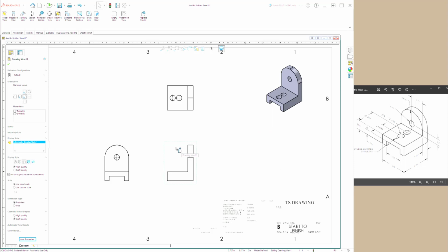So what it's telling us is that in here, it's in the hidden line remove. We want to show the hidden lines. So we want to make the hidden lines visible. On the left hand side, when I click the view, we want to choose hidden lines are visible, and bingo, the hidden lines are visible. Same here. All the views now update.